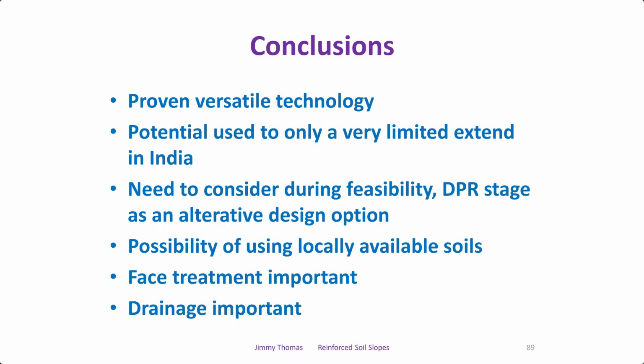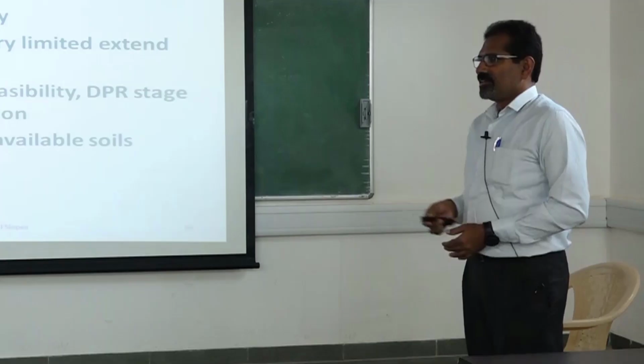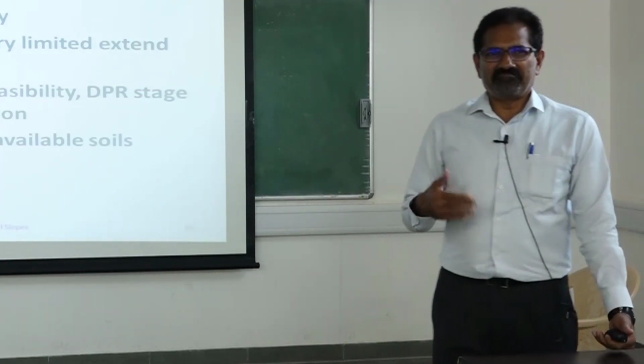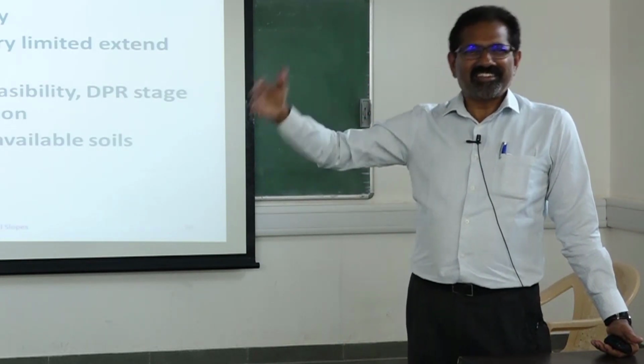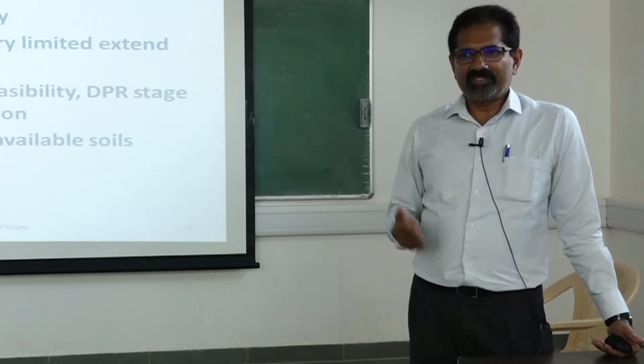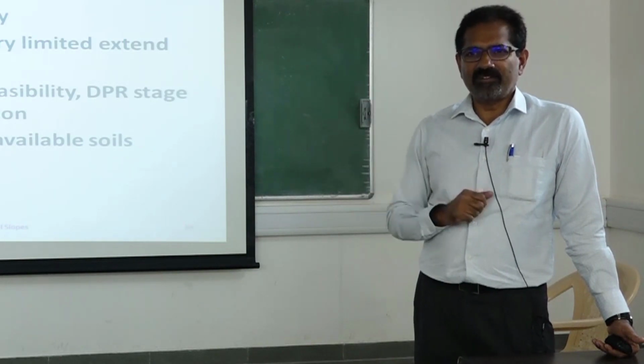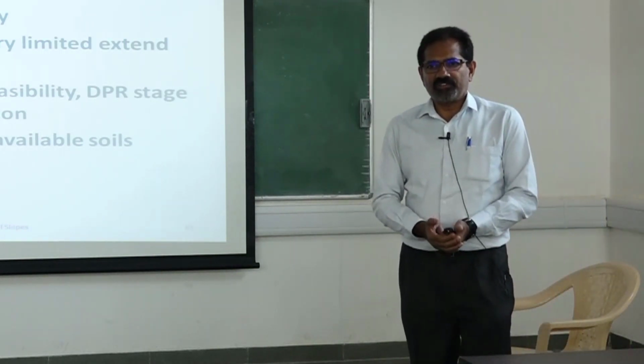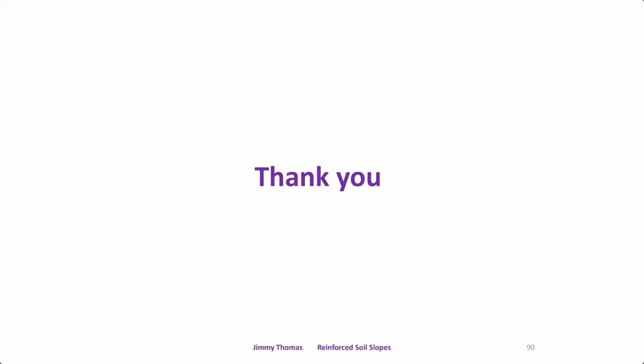To conclude, the reinforced soil slope is a proven, versatile technology. Especially in India, we need to explore this option more. The main advantage is using locally available soils. Here also, face treatment is important. Sometimes we put more emphasis on the calculations and design analysis, but detailing is also equally important. Proper construction and face treatment are very important. Then drainage is also very, very important. That I conclude.